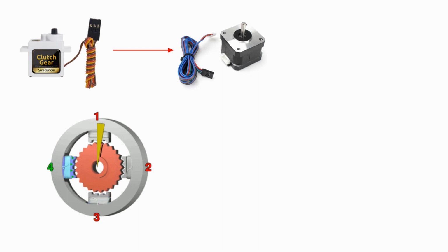Then, the bottom electromagnet 3 is energized. Another small rotation occurs. Then, the left electromagnet 4 is energized, again a small rotation. When the top electromagnet 1 is again enabled, the rotor will have rotated by 1 tooth position. In this example, there are 25 teeth. It will take 100 steps to make a full rotation, so each small rotation is 3.6 degrees. This is why it's called a stepper motor. It can control the angle very accurately. All 3D printers use stepper motors.